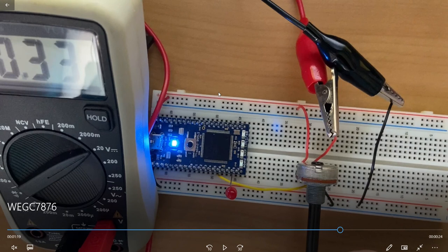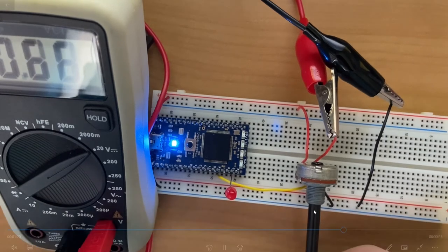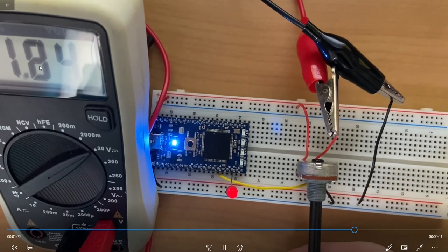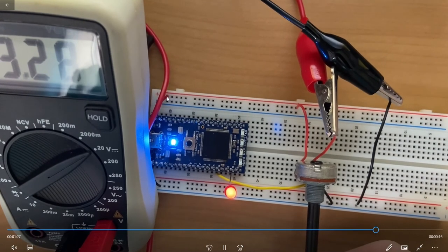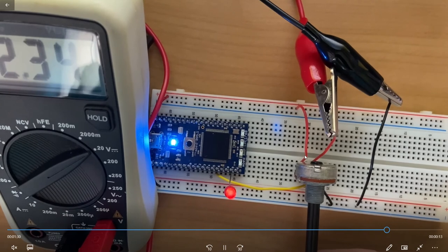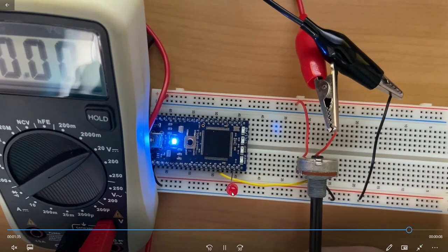Now just to show you, I've hooked up a multimeter here, and it's a little bit hard to see, so apologies, but I'm just checking the voltage that's going in on this yellow pin here. It's a bit hard to see, but that's where I'm checking it, in on that yellow line there, which is the analog value that's coming out of our potentiometer. And you can see, just as I'm changing this potentiometer, the voltage is changing from 0, which is ground, all the way up to 3.3 volts, which is the voltage that I'm supplying it with. And then we can still see the LED changing appropriately.